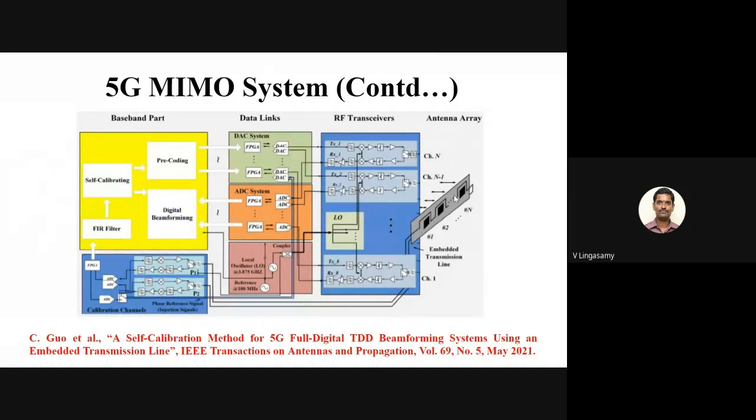So here, what will happen is, for example, a user is somewhere over here, 100 meters away. The user can receive and process a signal of minus 70 dBm, minus 80 dBm. That is the sensitivity of the user. So I have a path loss of roughly around 70 dB. My user can receive only up to minus 80, minus 70 dBm, let's say. So 70 dB path loss is there, minus 70 dBm.